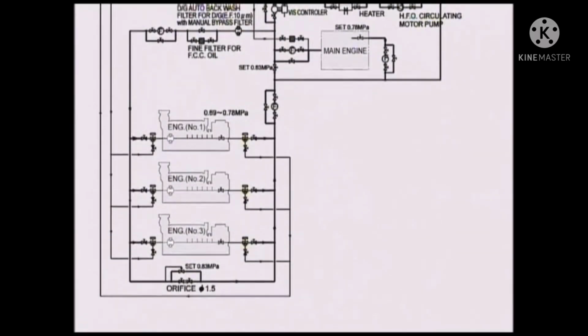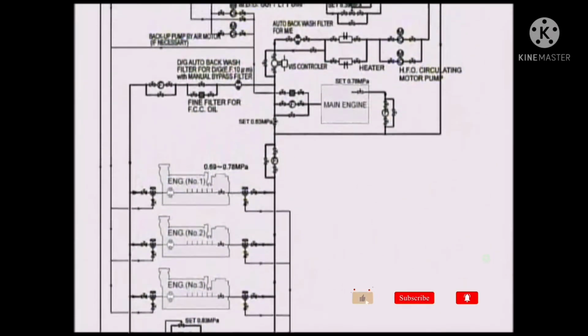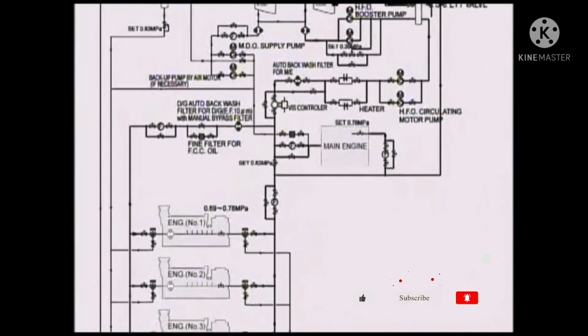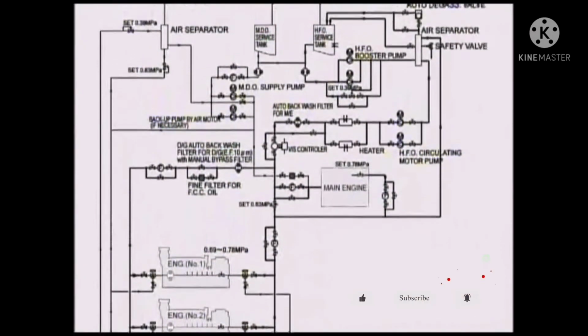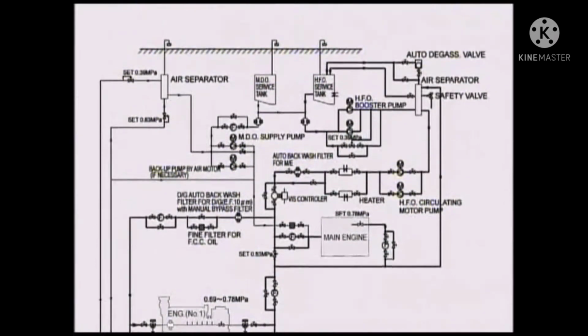Try to clean the fuel strainer first if the fuel oil pressure is out of the specified value. And for pressure adjustment by valve operation, you must properly operate each valve on the line after fully learning about the fuel line in the vessel.